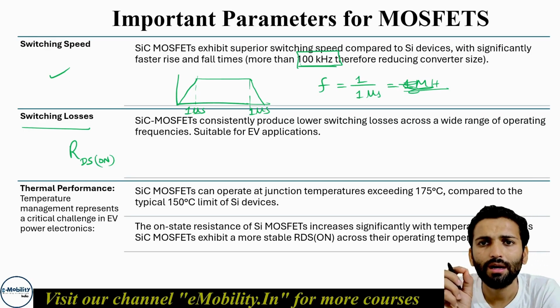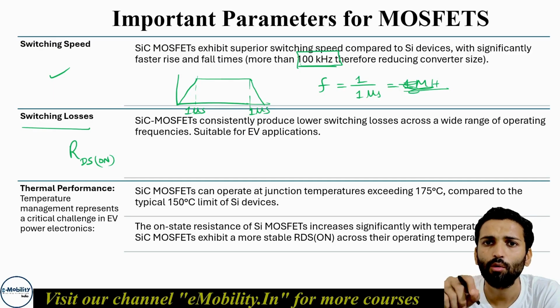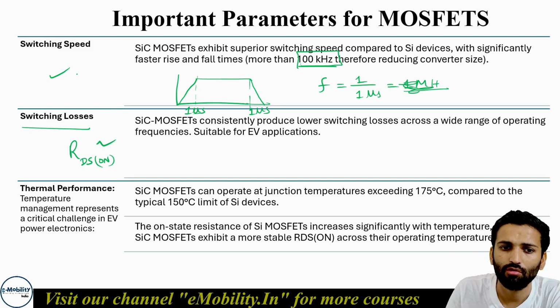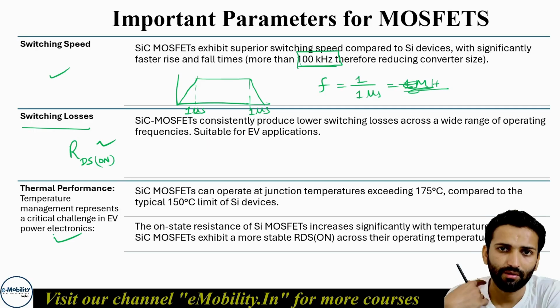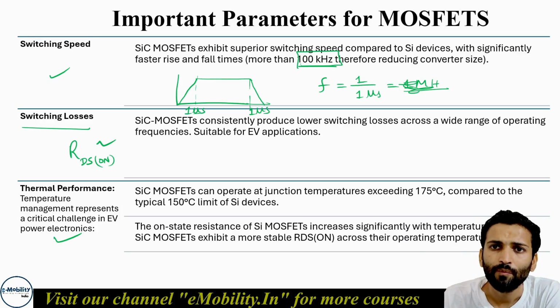So what is the RDS on resistance? This is very, very important because this RDS on will be creating losses during the on period. That means when the circuit is on, at that time it will be creating a problem by dissipating power. So RDS on is also very, very important. So one thing is switching speed, another thing is switching losses, which depends on the RDS on. And the third is the thermal performance: how the MOSFET is performing at 100 degrees, 150 degrees, whether the RDS on or the resistance is increasing, and if it is increasing, by what percentage it is increasing.